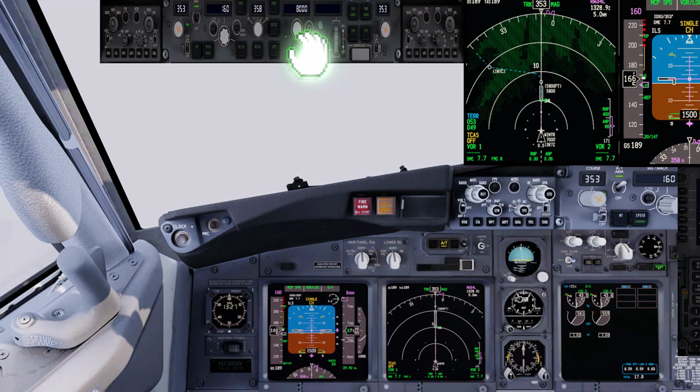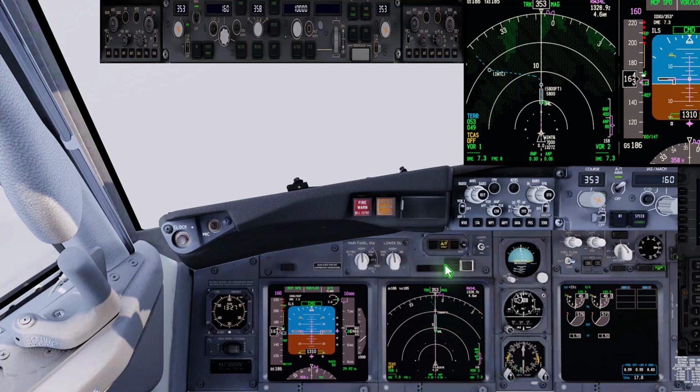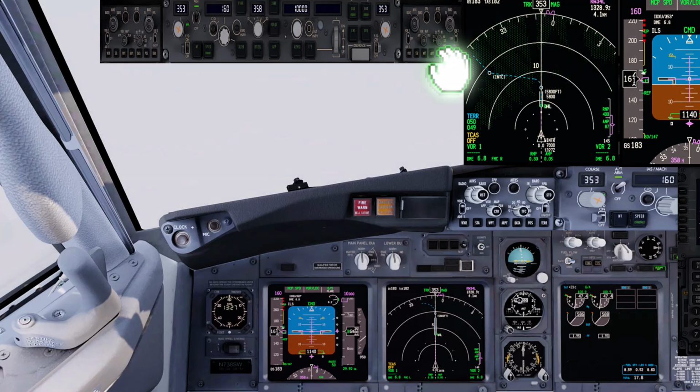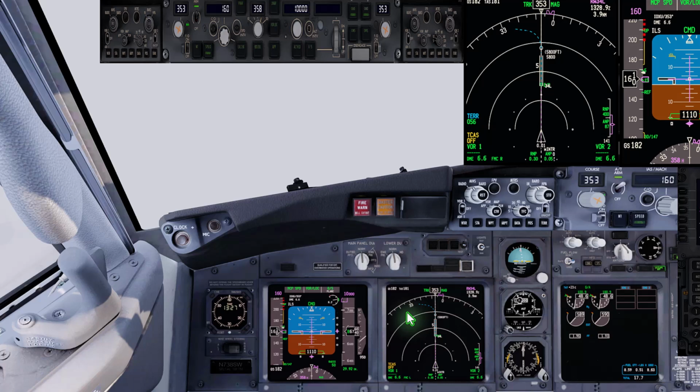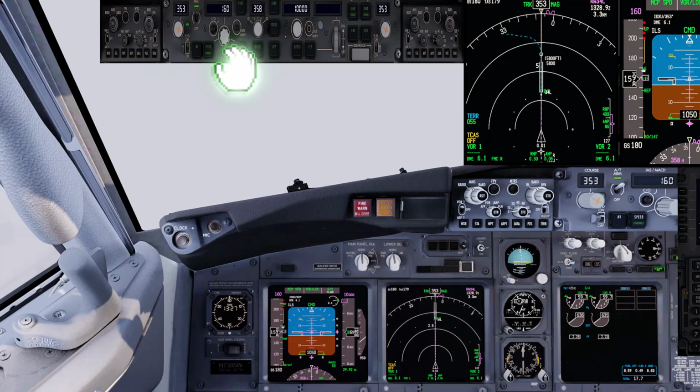But I can also set, since I have captured the glide slope, I can go ahead and set my missed approach altitude, which I can get out of my FMC. I don't have to go look at a chart or be distracted from my attention being here and here. I can go ahead and scale a little bit lower here on my pilot monitoring side. I can also do the same over on my side. I'm at the final approach fix. I'm a little slow on getting this accomplished because I'm explaining things to you, but we're going to go to final flap setting.